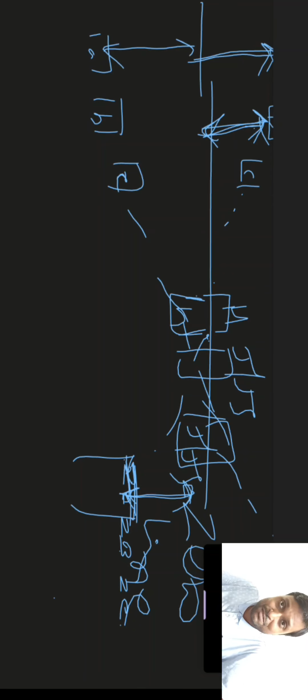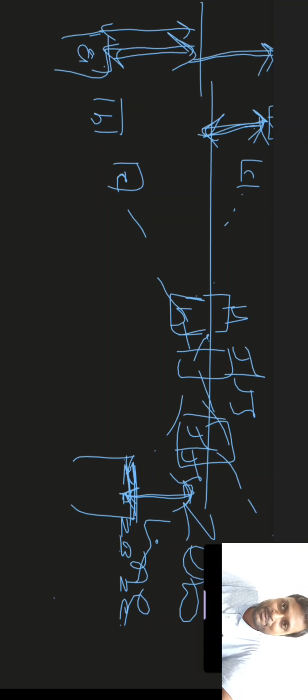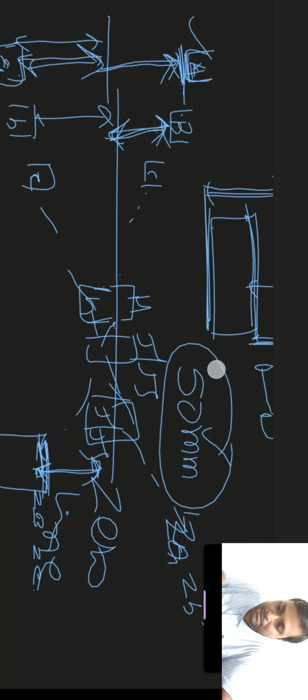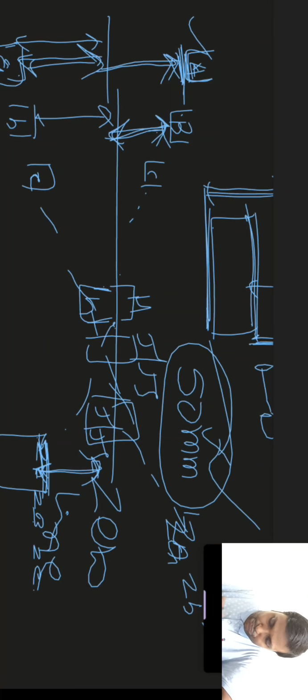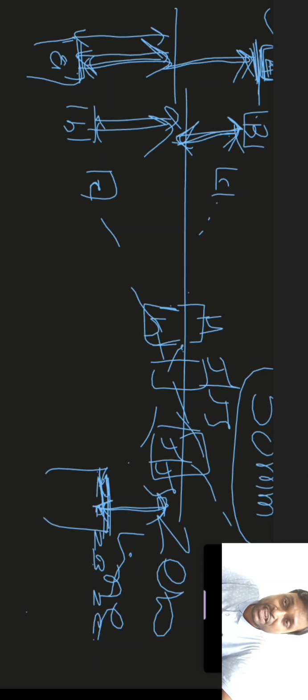For the fundamental deviation of the shaft also, A will have a particular fundamental deviation value. This A fundamental deviation will have a certain value, or you can say will have a certain distance from the zero line. Similarly, B will have another certain distance. If we take basic size at 50 mm, then absolutely the fundamental deviation of A, this distance, will be more than the absolute value of fundamental deviation of B.